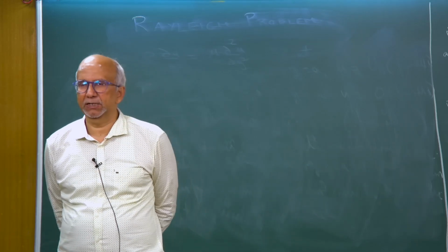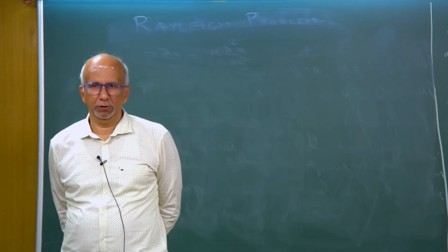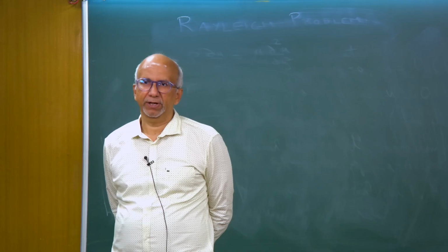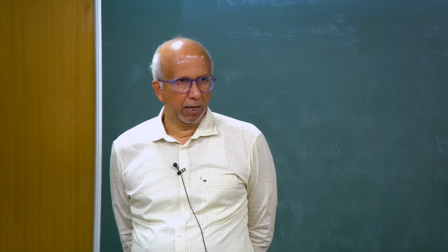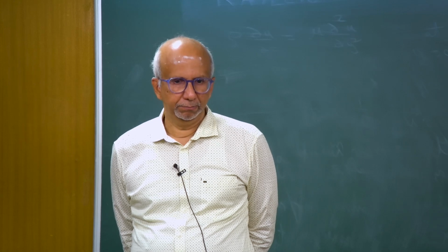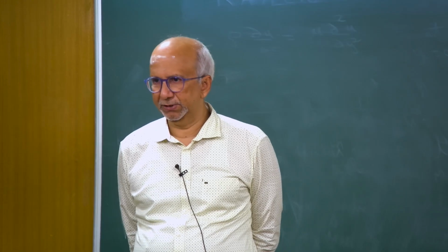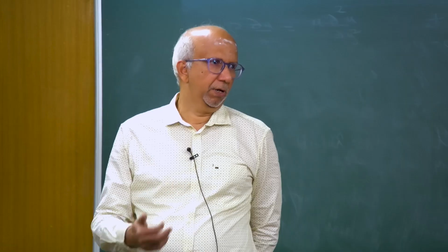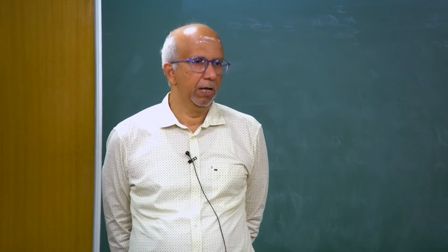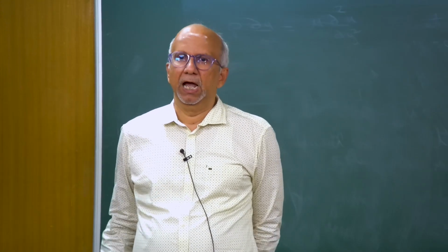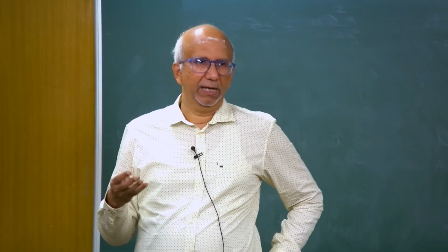You can use similarity transformation only for some class of problems, and I want to discuss a little bit about when we can possibly use similarity transformation, what the idea is. The basis for determining whether I can use similarity transformation or not is coming from the concept of making an equation dimensionless. Okay. So, when I make an equation dimensionless, you are used to using characteristic scales for making an equation dimensionless.